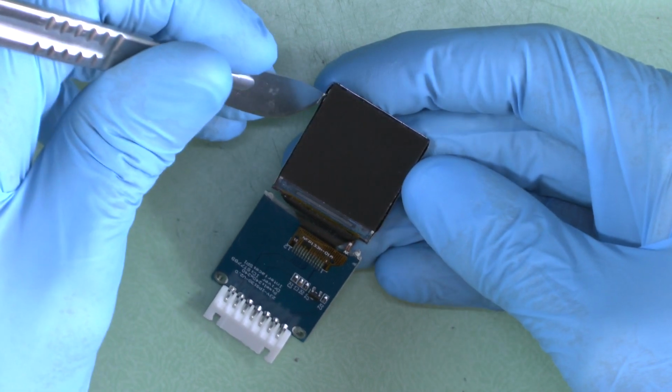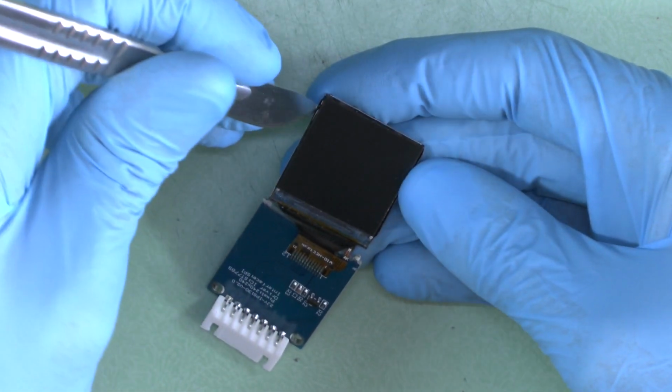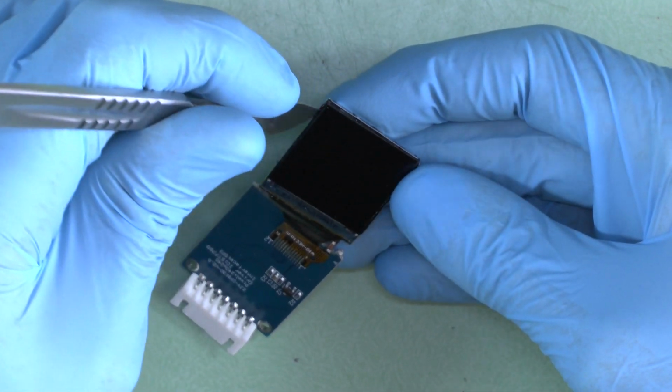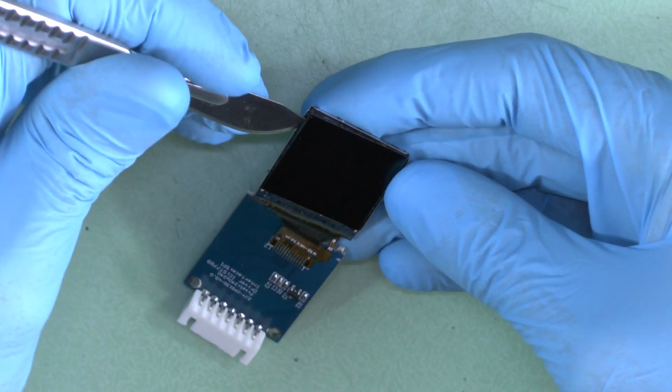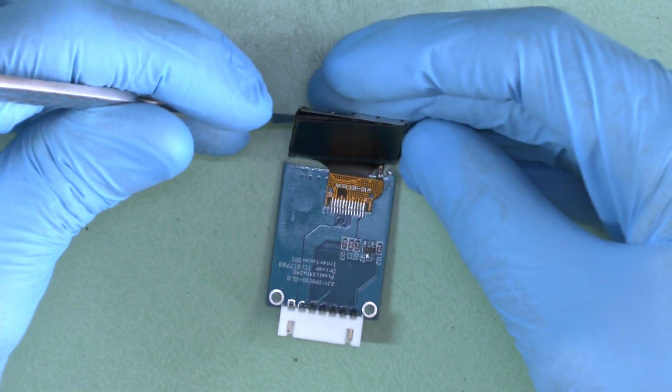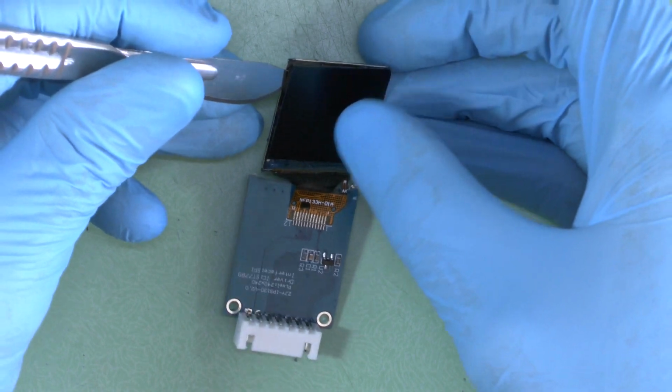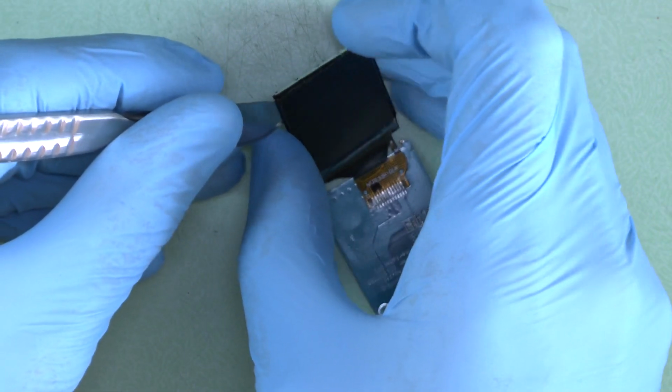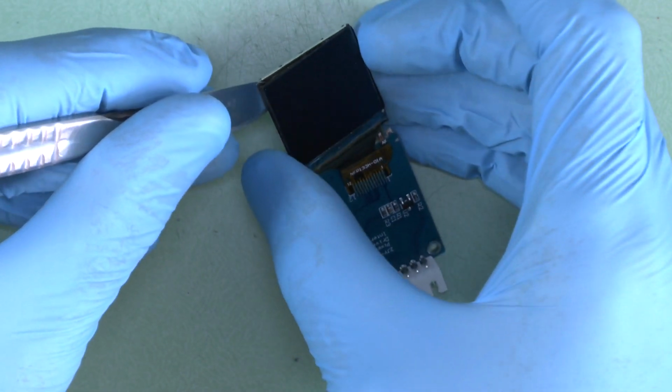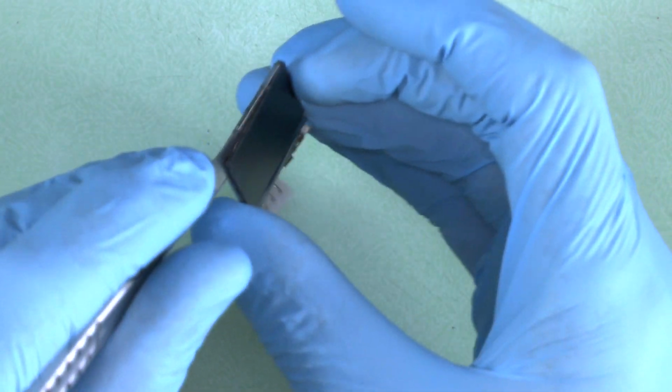Carefully, gently and slowly use the scalpel to lever the TFT plate out partially from the top and side. Don't lever it out fully or all at once, otherwise there will be pressure at the join of the main glass panel and the fragile connector extension glass, and it will crack.